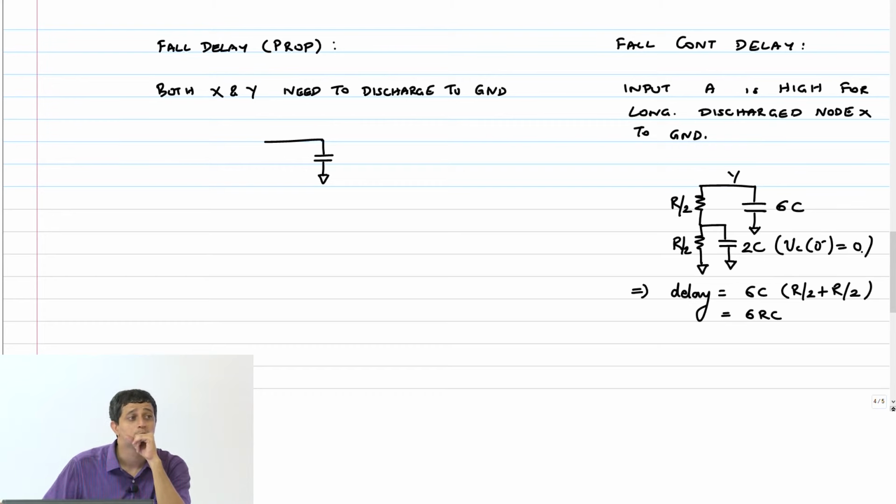True. So that's where the approximation that we made for this Elmore delay model comes in. It is true that this node, for it to accommodate some current, will actually bump up slightly. So this is only an approximate answer, not an exact answer.